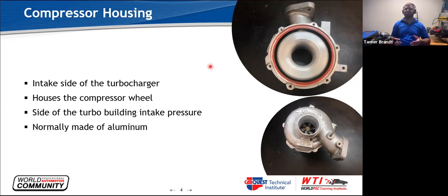If you were a rebuild facility, so let's say where I used to work, D&W Diesel, when we would rebuild these, some of the contour profiles we had measured out, and the welders would TIG weld those up and then they would remachine them. But for most of us, the guys that aren't rebuilding them, if something gets down in there and they get hit, you're screwed. That's pretty much it. If it has only hit a little bit and just left maybe some pits in it, you can take a flap wheel and clean it up a little bit, but you have to be really careful of the gap that you leave between the wheel and the housing, because if that gap gets too big, then you can have other issues.